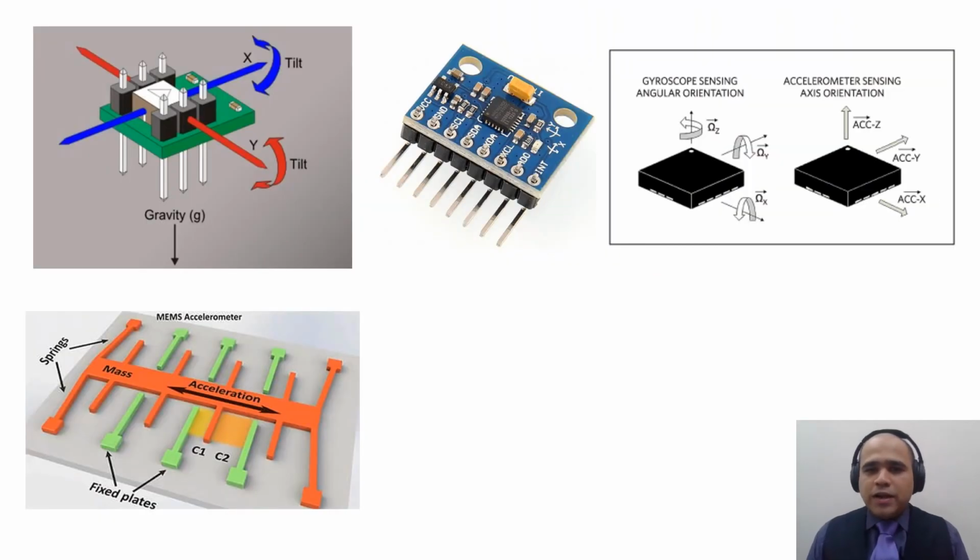The gyroscope and the accelerometer are the MEMS devices that we are going to see in the next talk on MEMS sensors, how they are manufactured and all. But basically, I give you an idea. These sensors detect an object which is moving up and down, left, right, or tilting. They use gravity and some internal mechanism like a spring arrangement, which is made using MEMS technology. So basically, for any motion or rotation calibration, you need these sensors. Nowadays, they are available in a combined package called an IMU, and this package has an onboard accelerometer, gyroscope, and magnetometer.